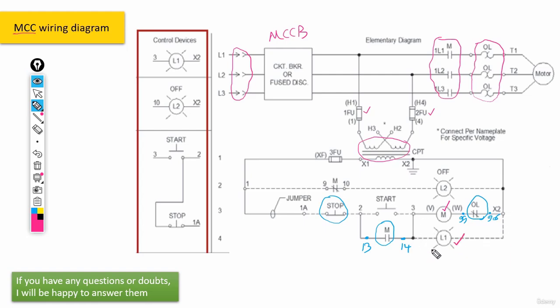Okay, and we also have another signal lamp set up here on this line. If the contactor was turned off, or if it was deactivated, for example, this contact here would close, and this makes the signal lamp turn on.